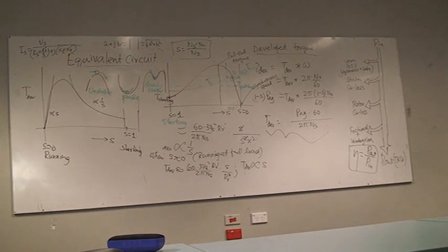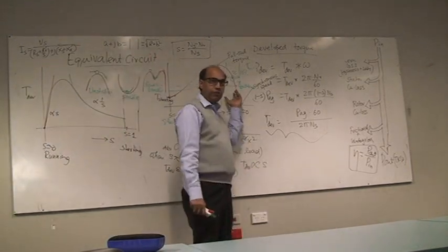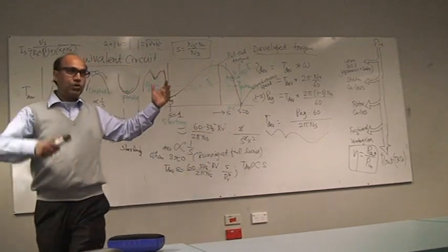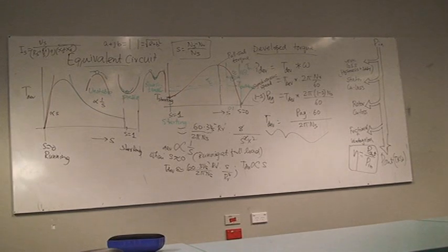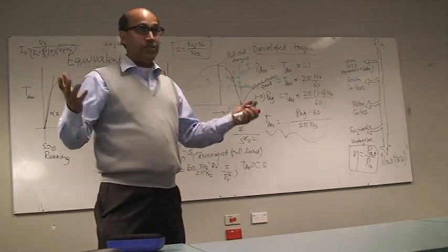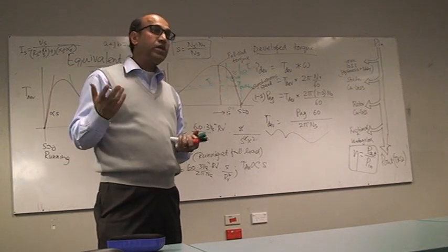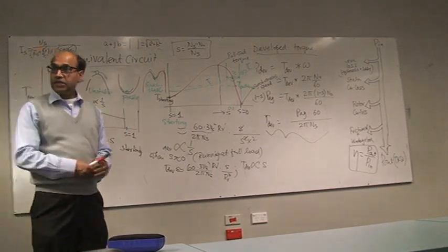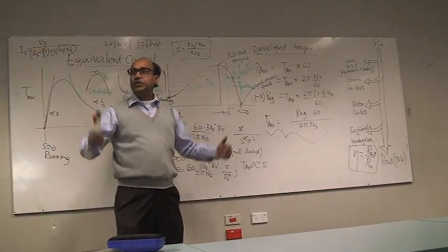So with the difference in S between the pull-out torque and the 0.1 S, would that be sort of a safety factor? Yeah, that's basically a safety factor. It comes down to whether you prefer a Russian design or a Japanese design. How much safety factor you keep, it all comes down to that. Anything Japanese made is very compact, but it does not give you much safety factor. But a Russian system never fails because it has like 3-4 times the factor of safety.